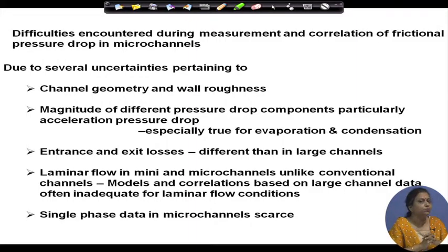It is encountered when the fluid which is flowing undergoes a change of phase. Why? Suppose it is a liquid which is changing into a vapor phase. Quite naturally, the moment the vapor phase is formed, because it has a lower density, it will try to flow faster through the conduit, and therefore, there is a change of momentum with the change in velocity of the liquid particles which are vaporized to the vapor phase.